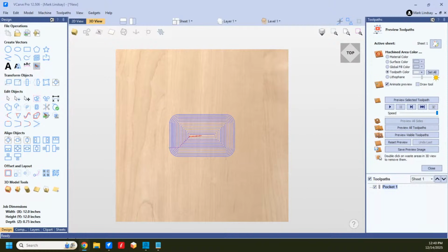You can see the pass depth of my 1/4 inch end mill is 1/8 of an inch. So I follow that advice. That's a conservative number to start with. From there, when I get comfortable with the machine and know what it's capable of doing, I can bump that up. My rule of thumb, after getting to know what the tool can do with whatever material, is to run a pass depth equal to the diameter of the bit. But only if I'm comfortable that my machine can do that and the material will allow it.